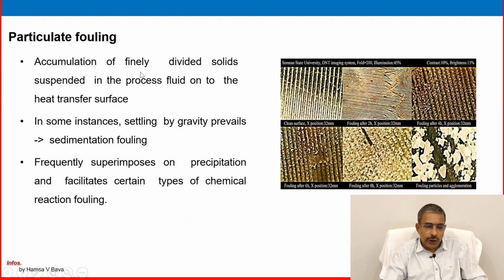Particulate fouling is the accumulation of finely divided solids suspended in the process fluid onto the heat transfer surface. Sometimes settling by gravity prevails, which is sedimentation fouling. It frequently superimposes on precipitation and facilitates certain types of chemical reaction fouling. This is a pictorial representation available in Google.